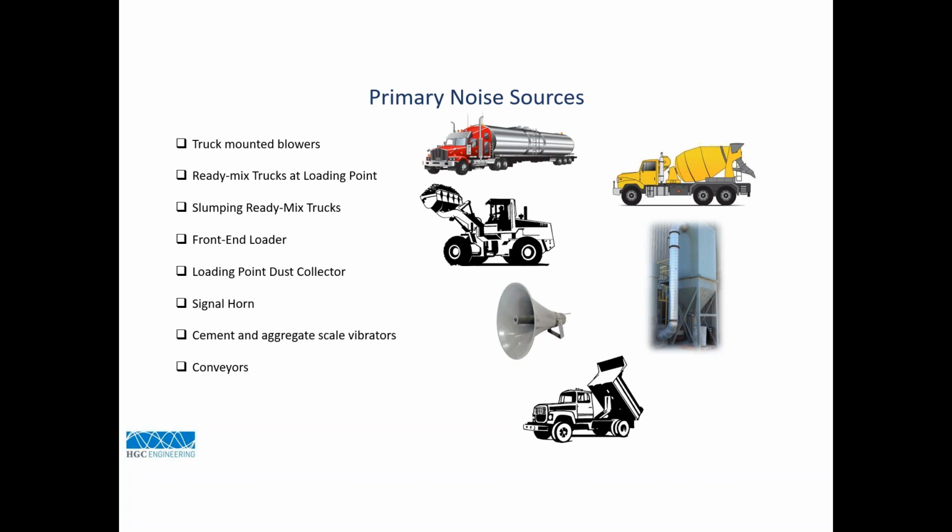The other sources in second place are going to be the ready-mix trucks, whether they are at the loading point while loading or at the slumping point. And you know that oftentimes when these trucks sit there, they rev up their engines, and that produces fairly significant noise. If we're going to look at some other sources, the front end loader can be a problem.